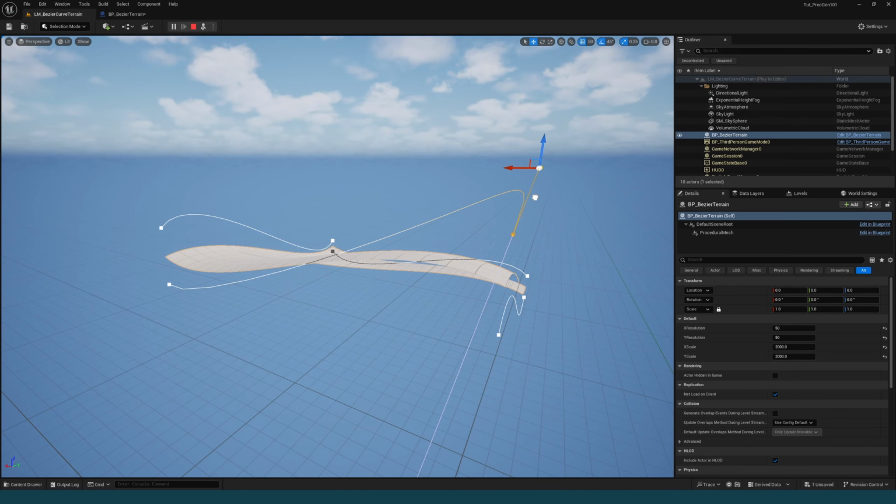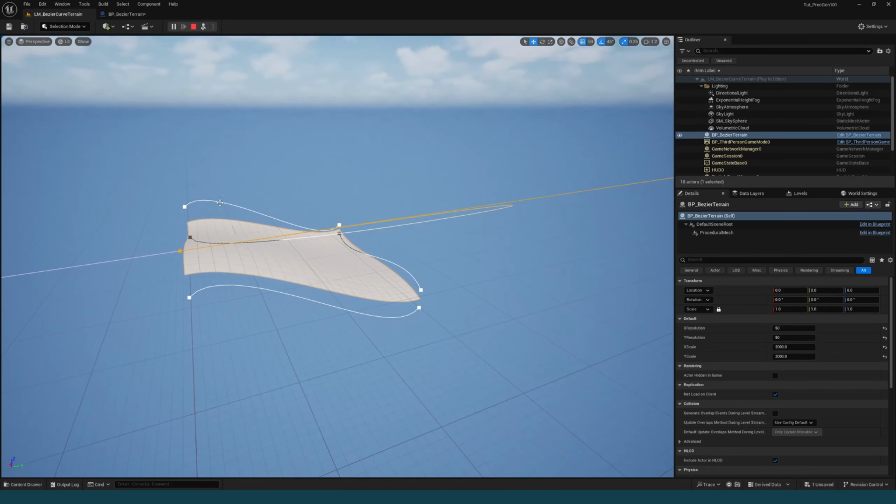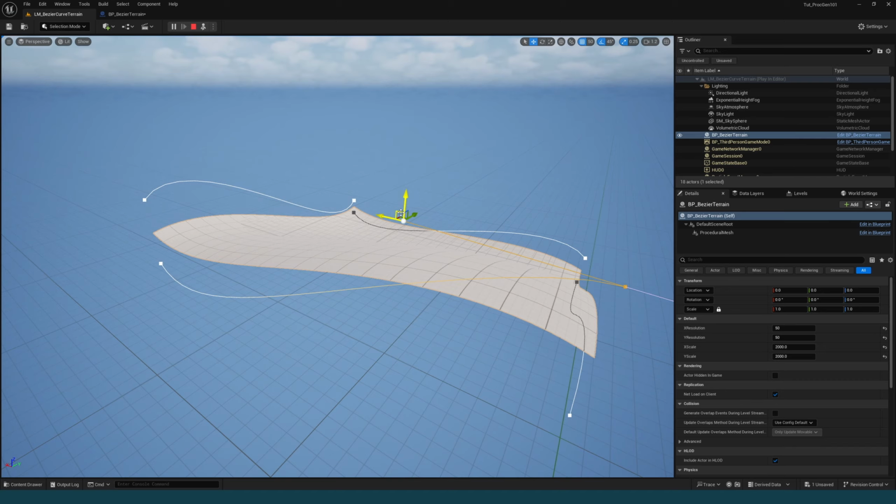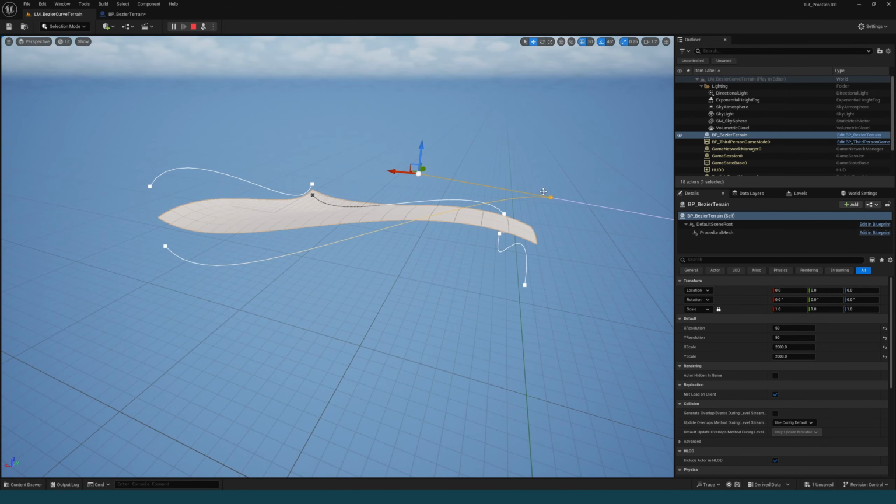We don't want it coming in, so we're not stretching our train over itself. So we'll want one of the directions to remain at 0 or remain at the position along our current curve. And then we can change the height and distance of this curve to change the overall shape of the Bezier curve.